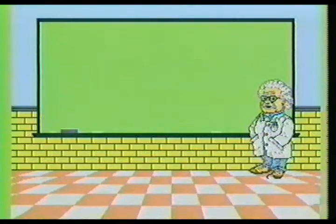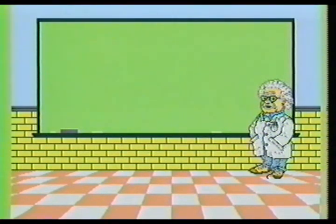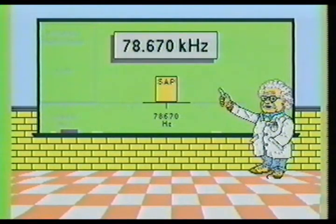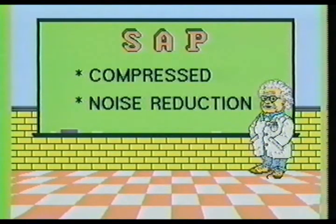At this time, we will pause for a review of the material just discussed. The letters SAP stand for Secondary Audio Program. The SAP audio subcarrier exists on the main audio baseband at 78.670 kHz. The demodulated SAP audio is compressed like the L-R audio signal, and in most television receivers, we use the same noise reduction stage to expand both audio signals.